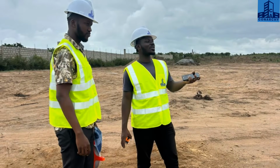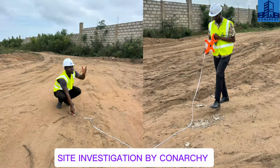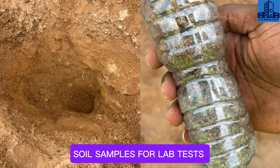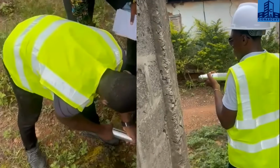They come to the site and do some site investigation. With the site investigation, that's where we actually know the type of soil we are dealing with, the slope of the land, and the various characteristics of the land. They also do soil checks, maybe bearing capacity, whatever it is. That's where we actually start the investigation.